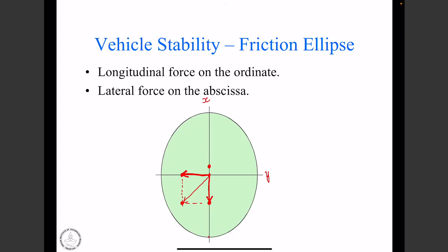So the brake system is designed such that we reach this extreme point. This is the boundary of the ellipse, which represents the dynamic limits of the traction force available at the tire road interface. The negative x-axis represents braking, so that's why we reach that limiting point there.